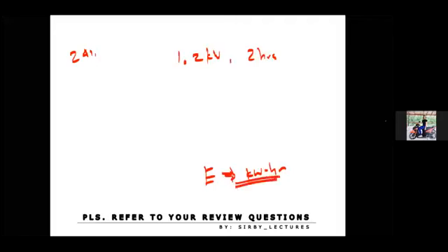So 1.2 kilowatts for 2 hours. And then 1,000 watts or 1 kilowatt for water heater at 3 hours. And another one, 1.3 kilowatts for toasters at 30 minutes, so this is 0.5 hours. If the average cost of energy is 10 pesos per kilowatt hour, what is the total cost of energy used in 30-day consumption?